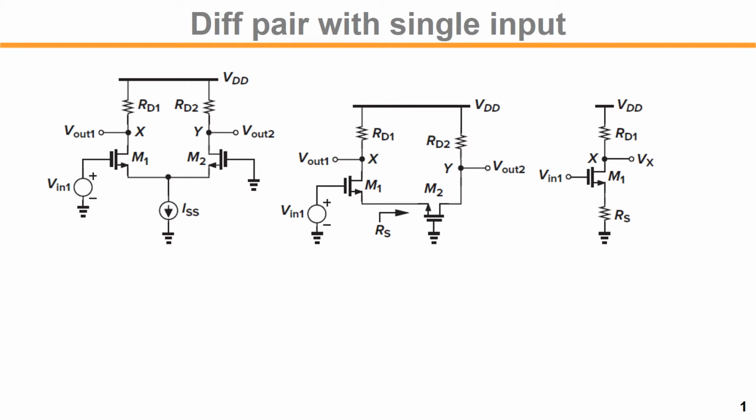In the previous small signal analysis, we assumed that the input is balanced, so the amount we go up on the left and the same amount goes down. But in this example, we are tying the other side to ground, AC ground, meaning DC voltage. So DC voltage, no voltage change. Only small signal variation on the left hand side. In that case, how are we going to find the gain?